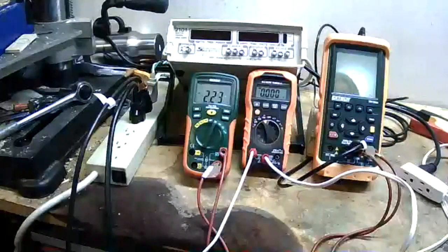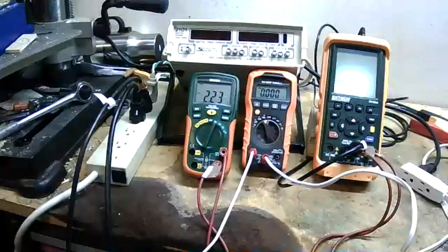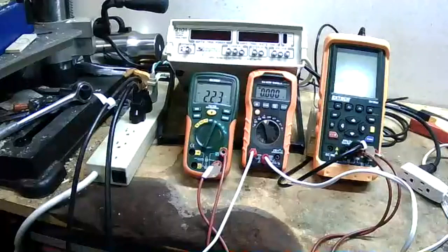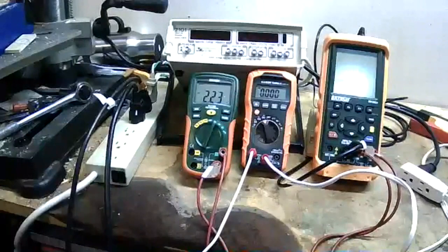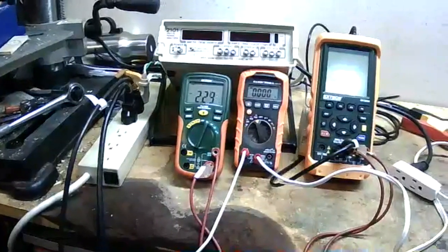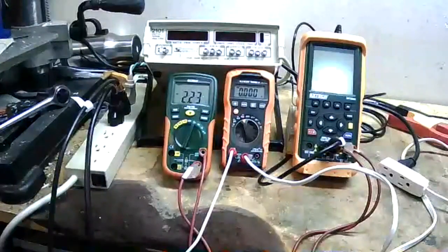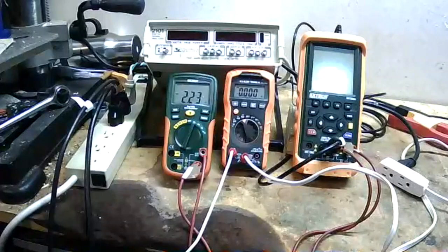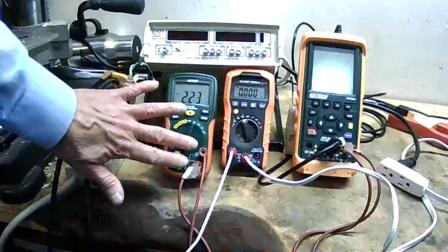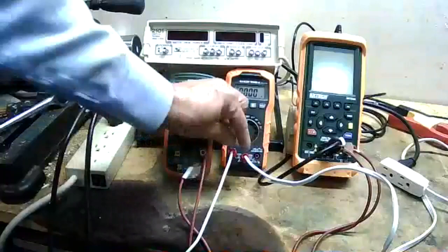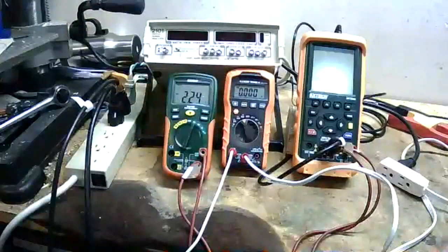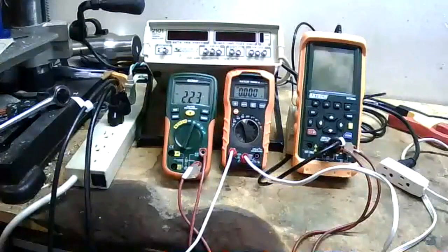So remember, to get current to the drill press, we need an almost zero impedance path. And that zero impedance path, low impedance path, is through the ammeter. Ammeters allow current to flow. Voltmeters are almost open circuit, so very high impedance where I'm measuring voltage, very low impedance where I'm measuring current. That allows the current to pass through.